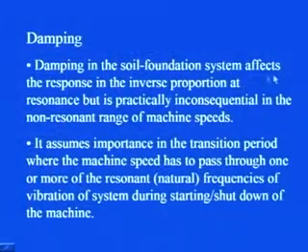Let us try to see some of the salient points related to this particular topic, that is damping. Damping in the soil foundation system affects the response in inverse proportion at resonance, but is practically inconsequential in the non-resonant range of machine speed.